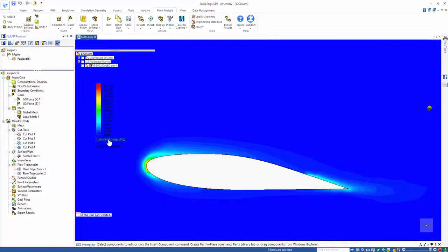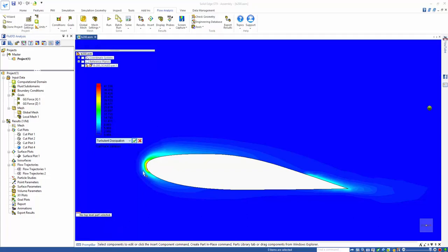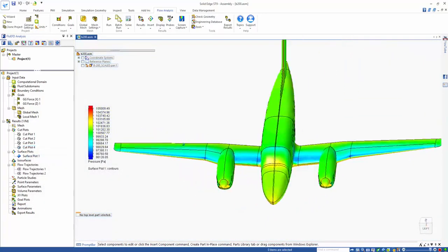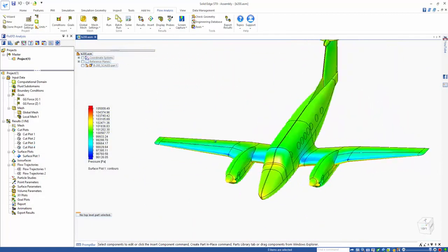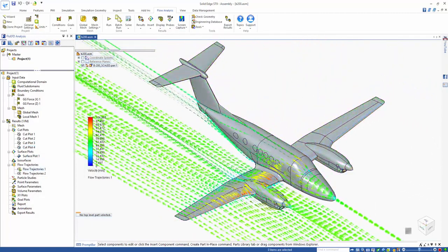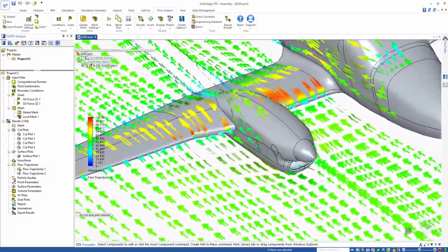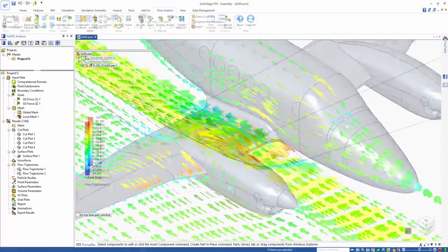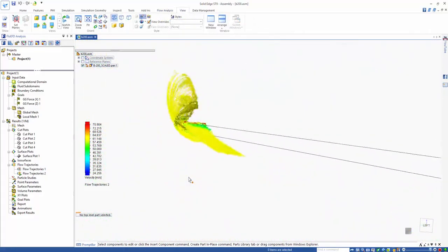Turbulence parameters can also be visualized. Here we have the turbulent energy, which can be seen along the top surface and trailing edge. Turbulence dissipation can also be seen the most along the leading, top face and trailing edge where the two streams combine. A surface plot of pressure shows the high pressure below the aircraft, which is what gives the lift. Flow around the aircraft shows the velocity vectors and is useful for determining flow separation or stall conditions. Wingtip flow behavior can be seen, which increases drag and reduces lift.